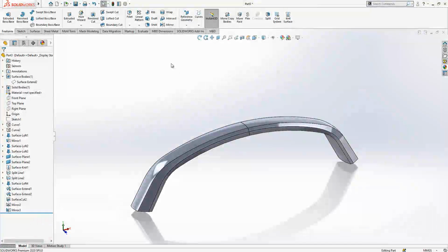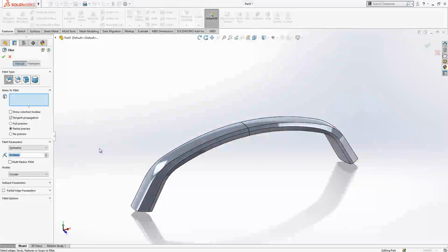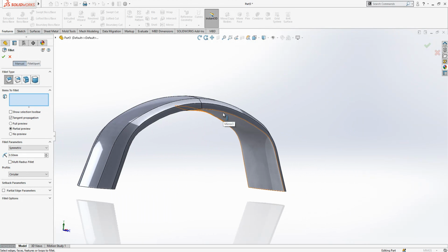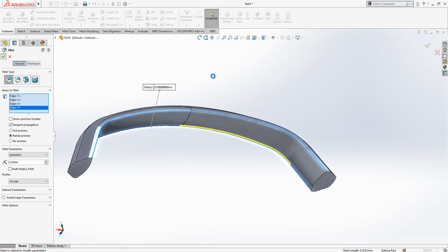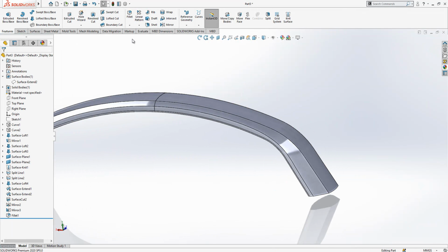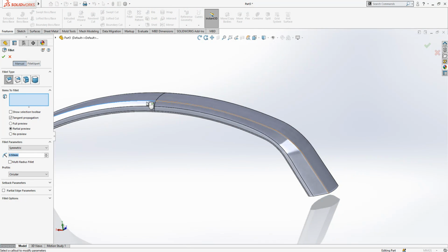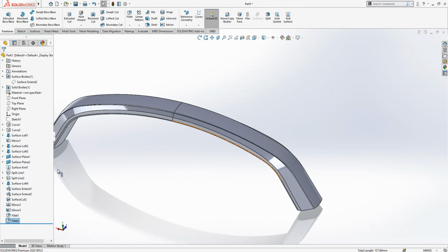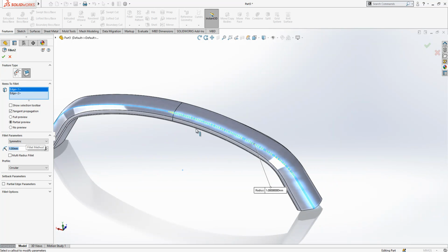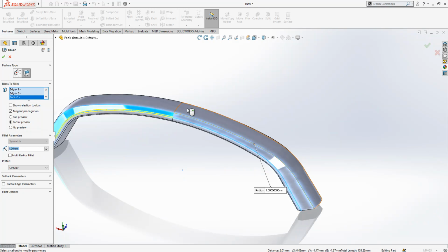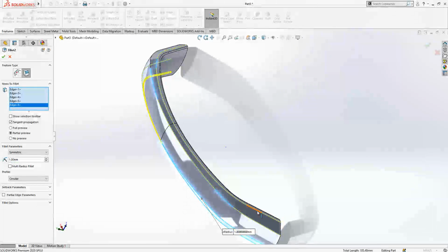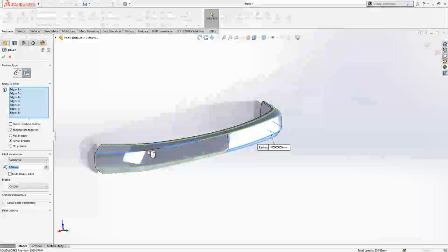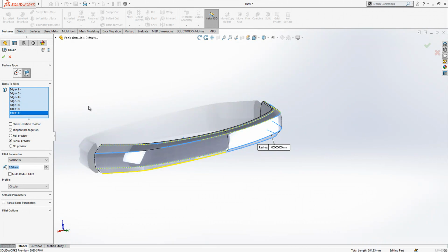So we can give some colors. Make fillet. Fillet 0.5. Here I will select these two edges. Here I will select these two edges as well. Radiuses are done. So right click, select tangency, sorry, a bit bigger radius here. Big one, big radius, and here as well, selected, not face, this edge, this edge, this edge, all the edges selected. So this should fix our problem.